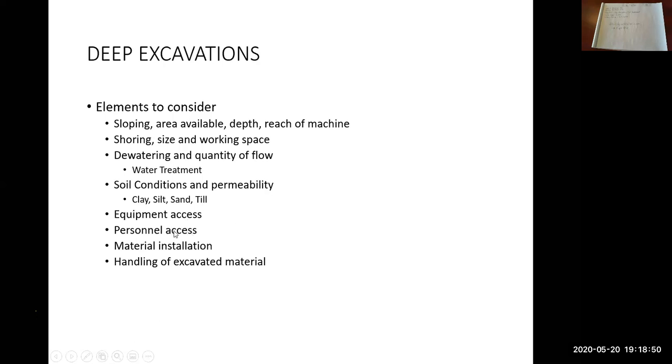Personnel access. So things like if you've got this deep excavation, for example, this 10-meter deep excavation, how do you get your crew down to the bottom of the excavation to start, you know, setting forms for footings, that type of thing. You need to get people down to the bottom. So if it's that deep of a hole, typically you wouldn't use ladders.